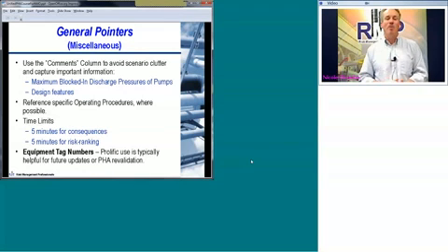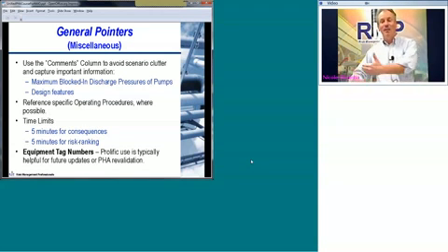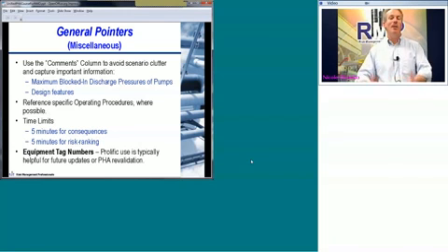Also, time limits. It's fair to tell the team that if they can't figure out a consequence of an event in 5 minutes, maybe it's a complicated sequence of scenarios or sequence of activities, it's okay to tag it as an action item. Note that the team did not understand the phenomenology associated with this, didn't understand the consequences, and make an action item for follow-up either during the HAZOP study or the parking lot.